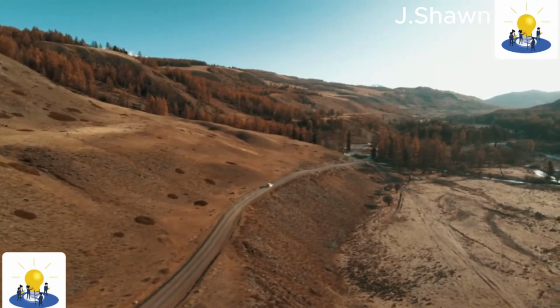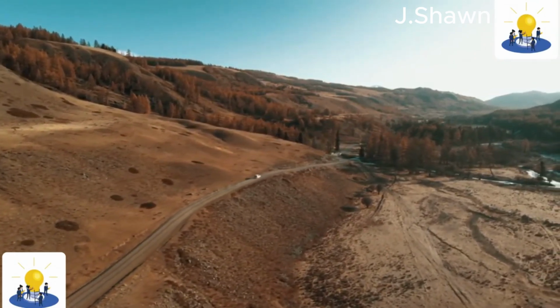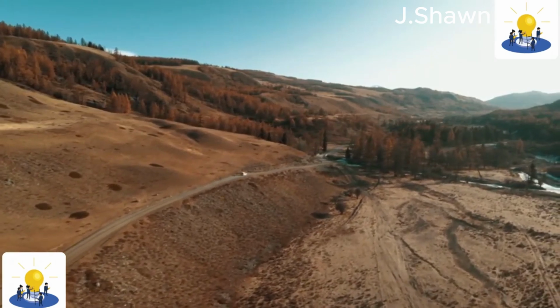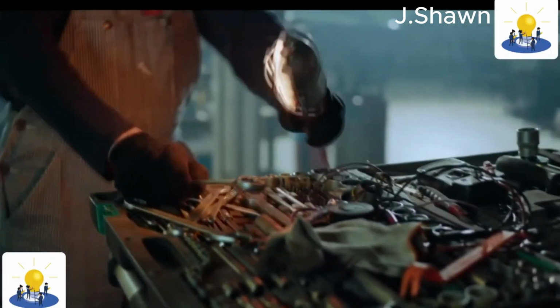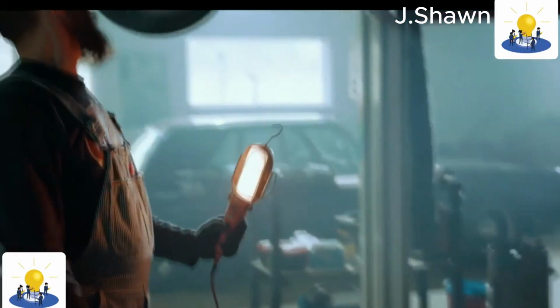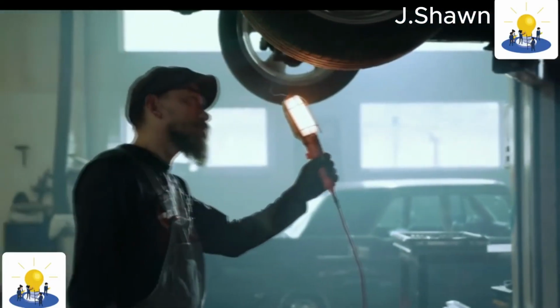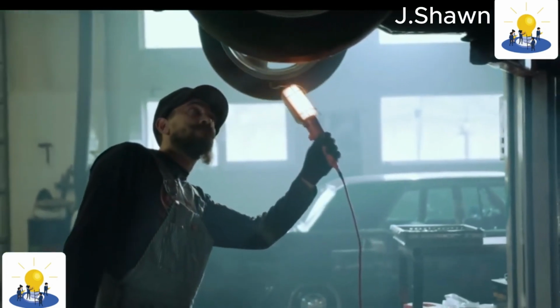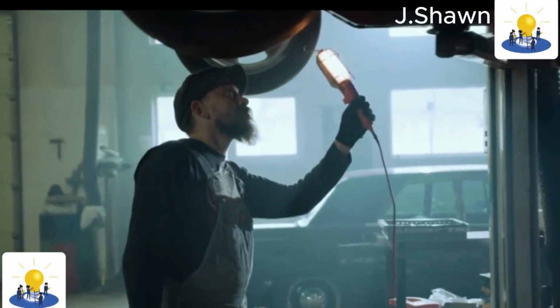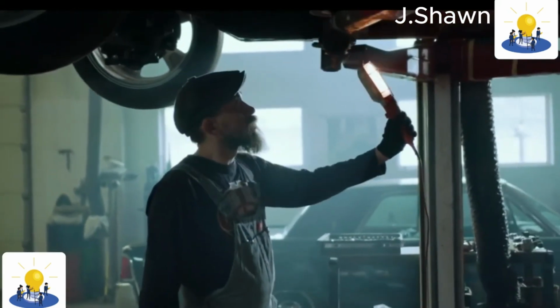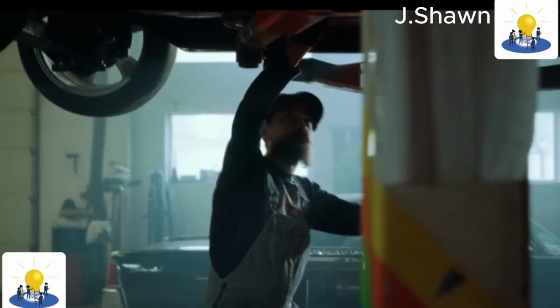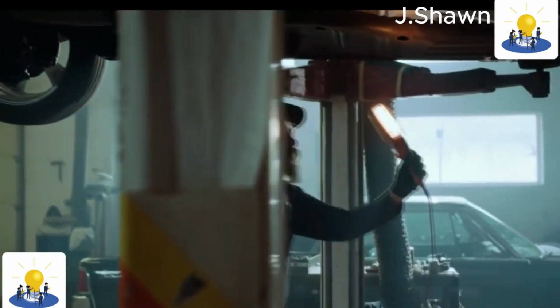Camber angle cannot change during body roll, and the geometric roll center of the suspension is always fixed at the physical axle midpoint, limiting suspension tuning options. Furthermore, the roll center moves in reaction to road irregularities. Toe is typically fixed at 0 for a live axle, and dynamic toe control is difficult to implement. The mass of the beam is part of the unsprung weight of the vehicle, hurting ride quality.